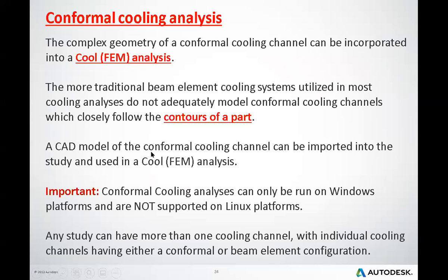A CAD model of the conformal cooling channel can be imported into the study and used in the Cool FEM analysis. So we have to set up the Cool FEM analysis in Moldflow to use this technique. The important thing we have to take care about is that conformal cooling analysis can only be run on Windows systems and is not supported on the Linux platform. Any study can have more than one cooling channel, with each individual cooling channel having either a conformal or beam element configuration. That's the detail of conformal cooling.